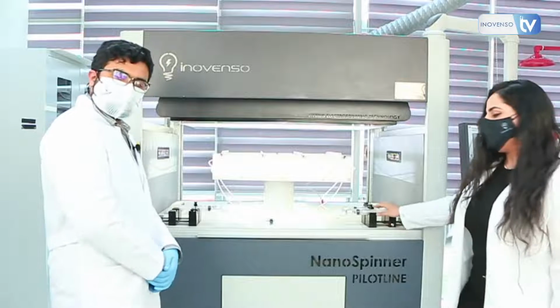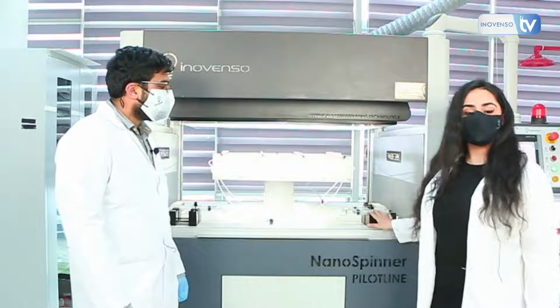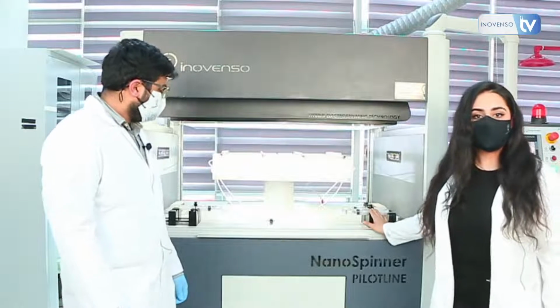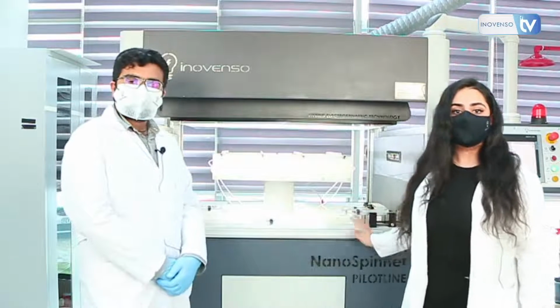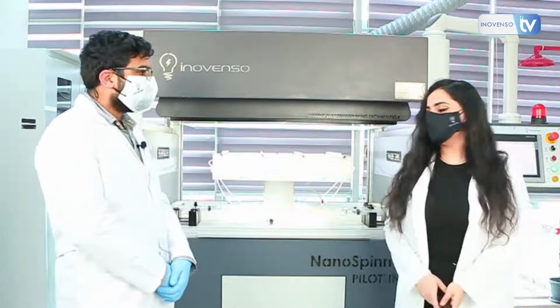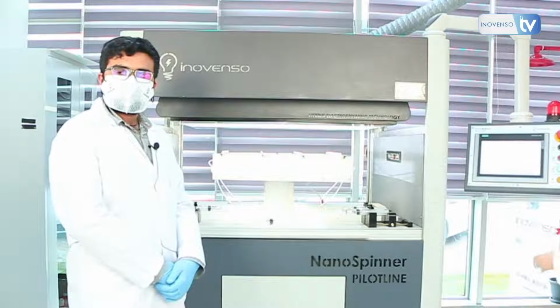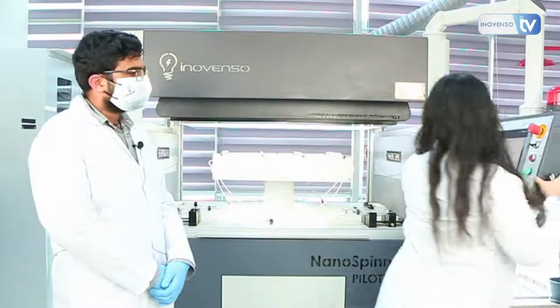Its unique design enables the production of nanofibers and composites. It has 4 syringe pumps. As you can see from here, we have 2 on each side. On all the syringe pumps you can use different polymers independently, controlled by the touch panel screen, as you're going to see right here. We also have 4 high voltage power supplies down below. And if we talk about the touch panel screen, I would like to briefly mention and show you some.